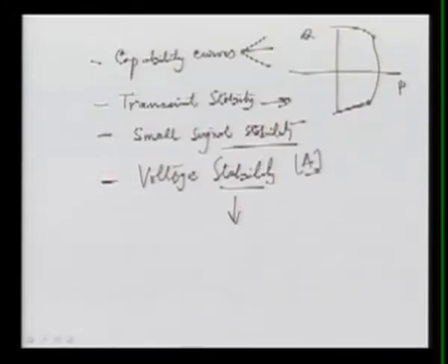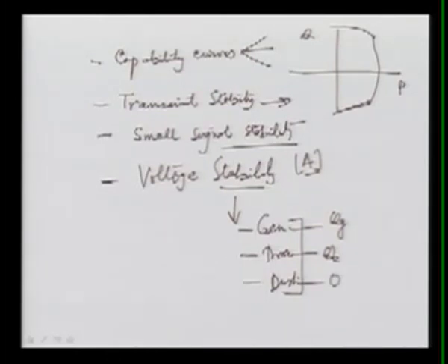Again, at the generator level we can do something, at the transmission level, and at the distribution level. From these three angles, here we can set the QGs at generation, here we can go for a Q source or some capacitor or static var compensator, here we can go for the OLTC, and as well as the P demand if you can go for. So these are the various control measures by which we can improve the voltage stability of the system.